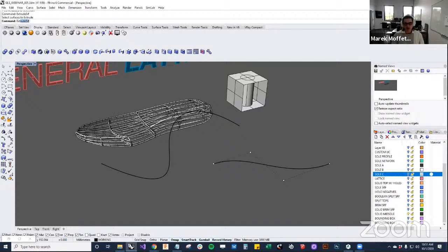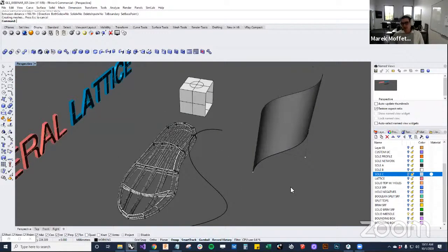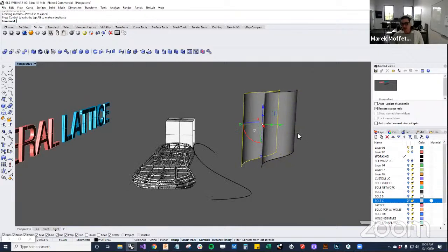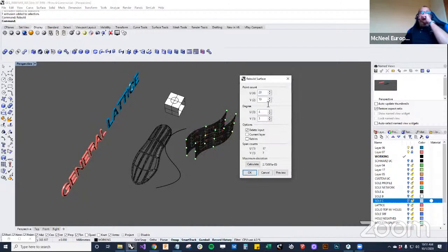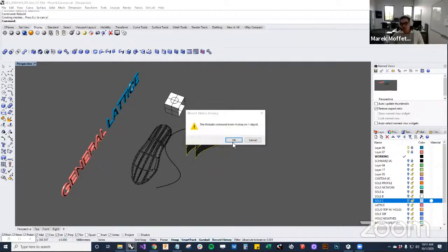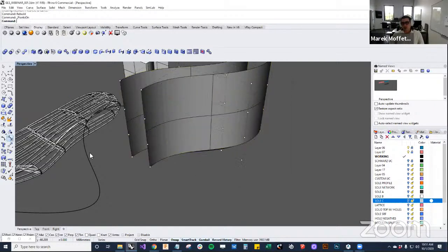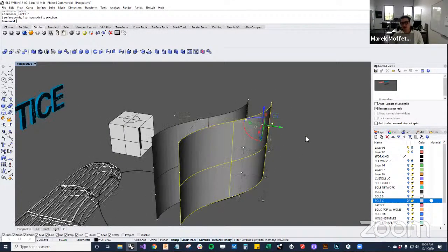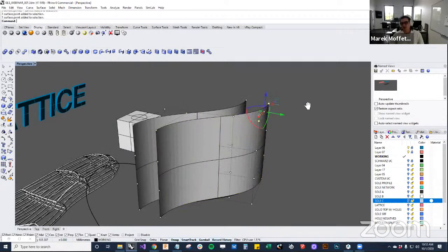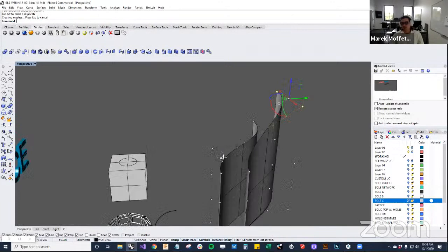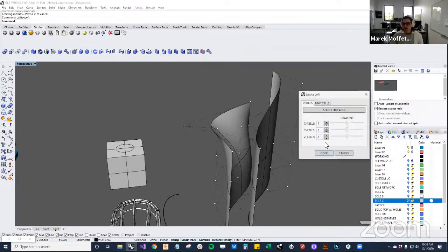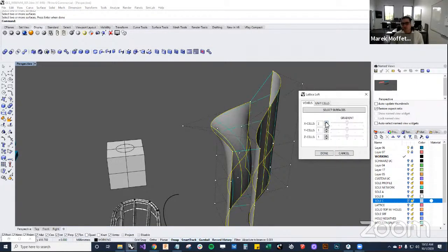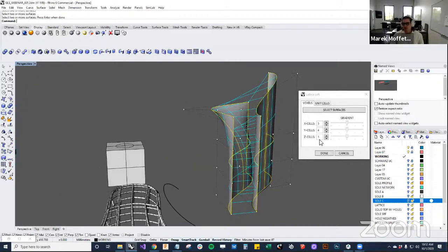So I'll just do extrude curve here to create this sort of facade. Do something like this. I'll do a quick copy and paste, and maybe do a rebuild. Just do 4s, and we'll turn the points on. So if one could imagine this as a decorative wall facade potentially, maybe something odd like this, you could use Lattice Loft and start to explore what something odd like this may look like.